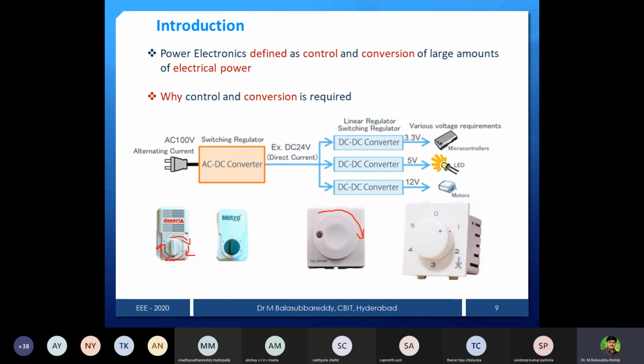So here also you take different tappings. Alpha will be 180, then 140, 160, 90 and then 0, something like that. So then what will happen? If I keep on changing the step, instead of smooth variation they made it in steps, and you can move that. Some particular alpha will be there and the corresponding voltage will be connected to the machine.